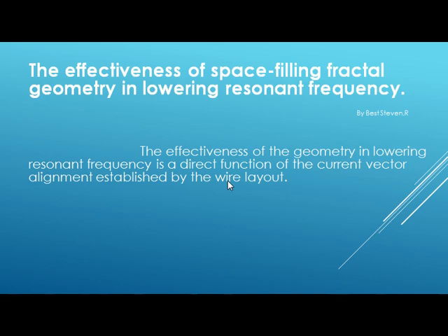In this way you can take a 5 kilowatt power amplifier and get a 10 kilowatt effective radiated power because they're tuning the antenna elements during transmission. So with the fractal, we've so far considered the idea that we would just print it on a printed circuit board. But if that printed circuit board were mounted at the focus of a parabolic dish, then you might be able to get a directionality that gives you a substantial gain.